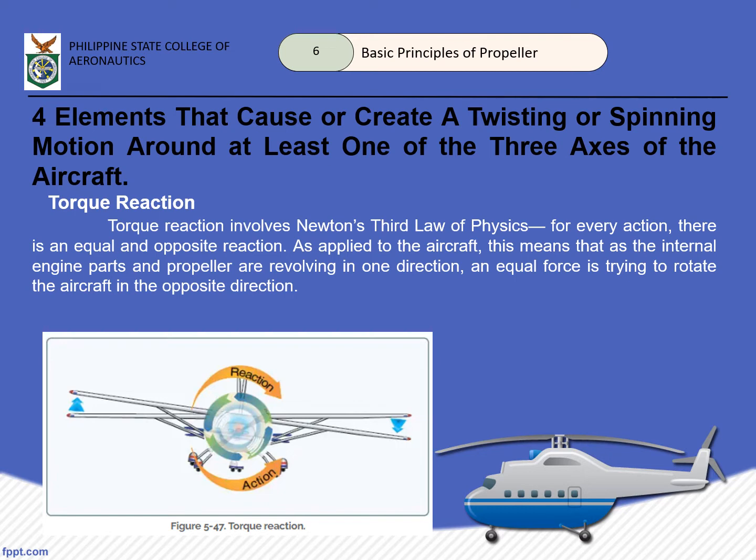Depending on our manufacturer, designs to counter this effect are introduced. Some aircraft are designed so that their left wing produces more lift when at a perfect cruising speed. This is for fixed wing, okay? Or for a few models, they often offset the engine to counteract the reaction of the weight. So, those are usually the designs that are incorporated to counter this torque reaction.